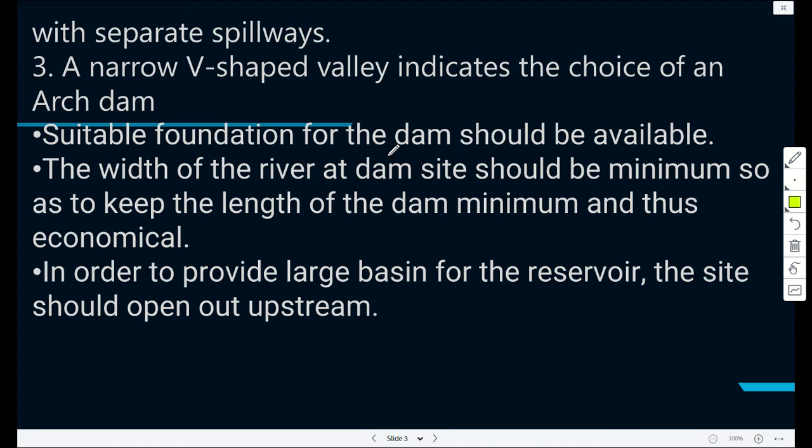Most of you can remember, I think in the previous three, four or five years, there was a dam in Nakuru that collapsed, and that is basically because water was passing through the structure at uncontrolled rates. Eventually, erosion kicked in, and then water could not be controlled, and people lost lives. So this is the point. You must control the seepage, you must control the erosion.